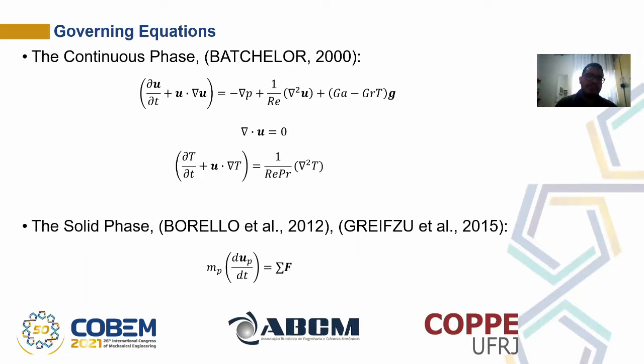Here's the introduction of the governing equations, which is basically the Navier-Stokes equations in the non-dimensional form. Here it's modified to aggregate the expansion problem and also the advective problem.